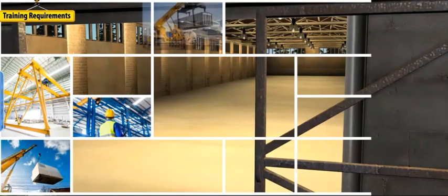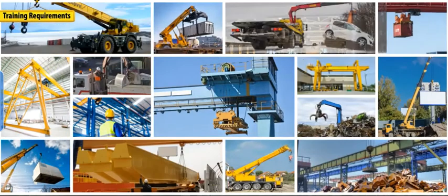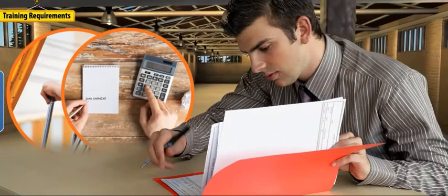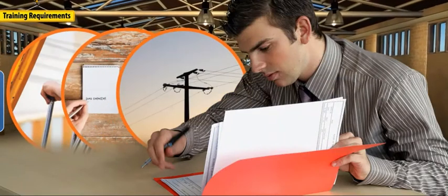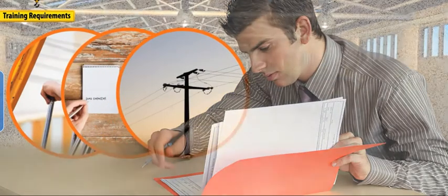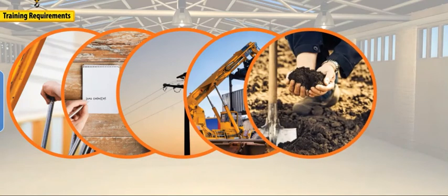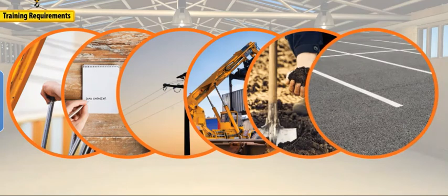Before you can operate any cranes on your work site, you'll need to be trained over the specific crane you'll be working with. You'll have to take a written test over your crane's controls, calculating your crane's load capacity, any procedures for avoiding power lines and other hazards on the site, specific procedures for moving and operating cranes and loads onto the site, and other specifics about your work site, such as the characteristics of the ground or other surfaces the crane will sit on.